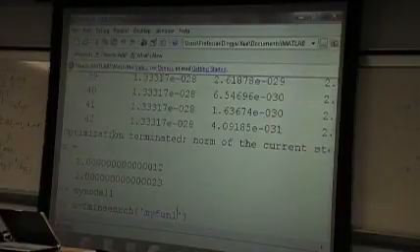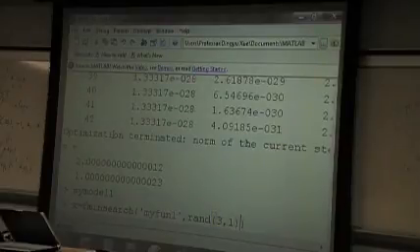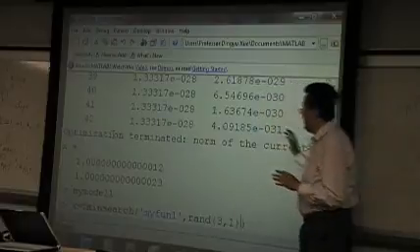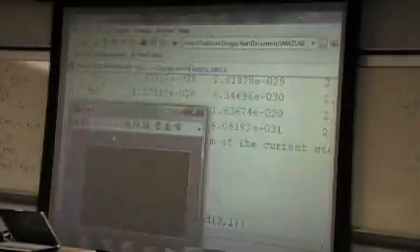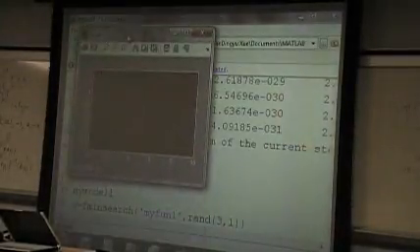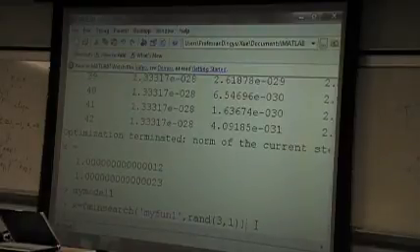And for the initial searching point, we have 3 parameters. We can generate 3 random numbers for the KP, KI, KD parameters. And now we can open the scope here and run the optimization problem.